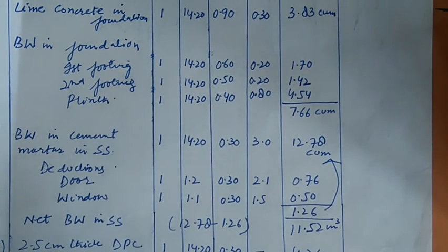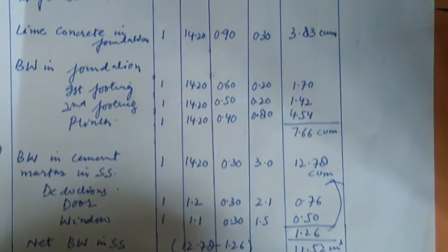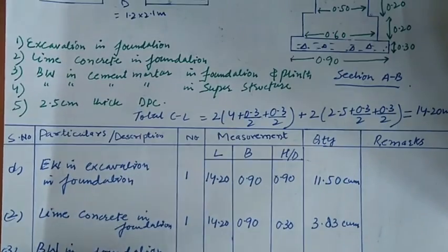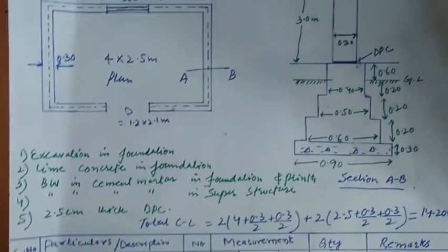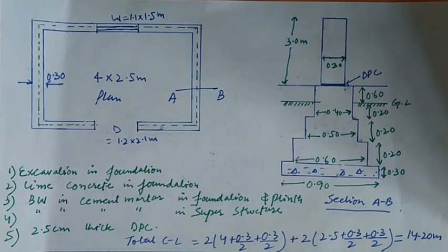So this is how quickly we have solved the same problem with this method, because when there are no cross walls or no partition walls in our structure like here, then we can opt for this method. This will be very quick. But when there are the junctions or the partition walls, it will consume some time there. Talking about the accuracy, the long wall and short wall method is more accurate compared to this method.